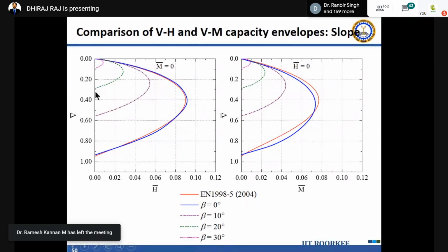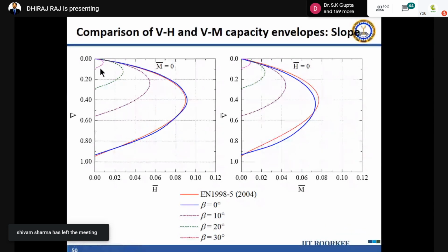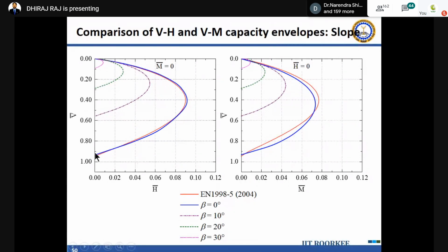Even if you are keeping the foundation at 1/3, still the foundation is not capable of taking any load. The retained capacity is just 10% of the vertical load of the foundation on flat ground. So these methods are not applicable here also.